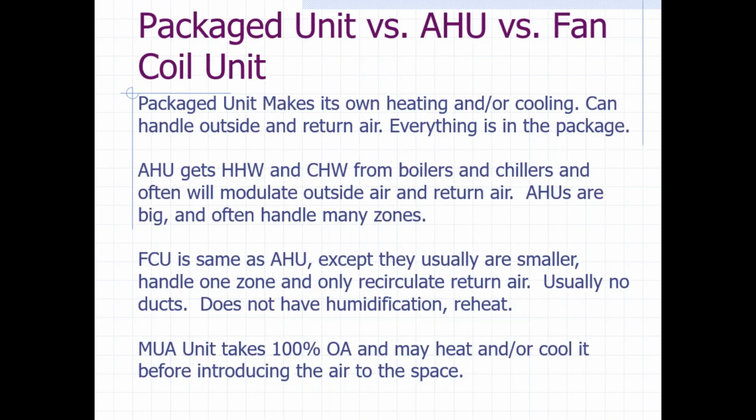So what a package unit is, ideally, is that all the heating and cooling is made in the unit. That's the idea, okay? It would have what they call DX cooling, which means it has its own refrigeration cycle, but it also could have a furnace. Now, a package unit might do cooling only, so it might not have a furnace. But everything's supposed to be there.